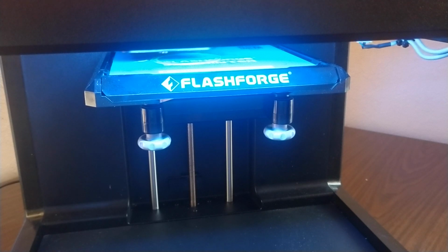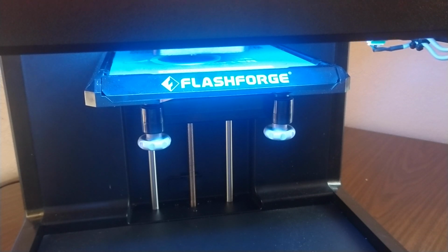After starting the print, it's best to watch the machine for at least a few minutes to make sure it successfully lays down the first layers of material. If I notice a problem, for example, the material isn't sticking to the bed or the filament gets jammed, I can stop my print, address the problem, clear the material, and start the job over again.